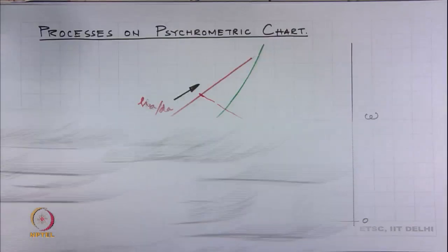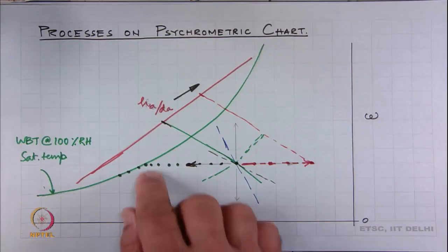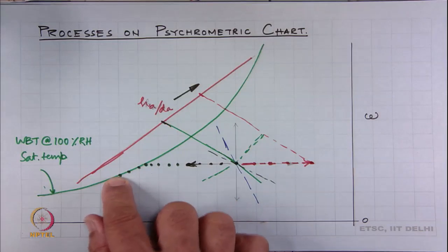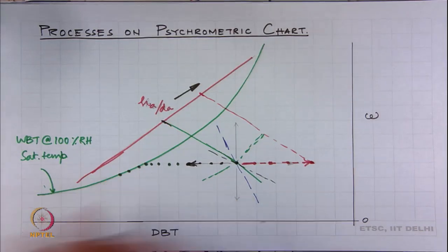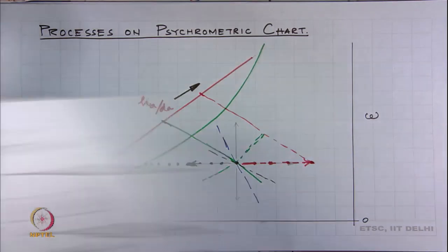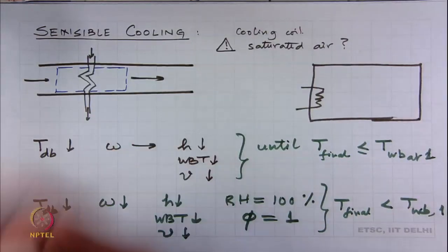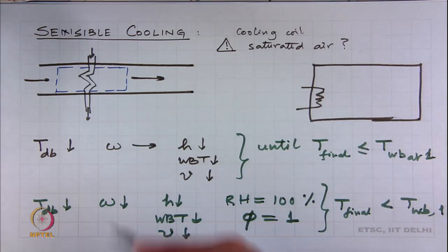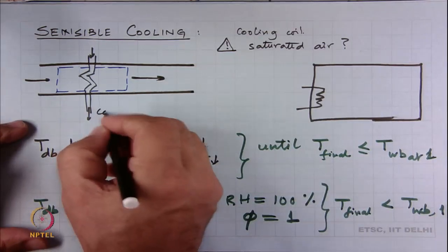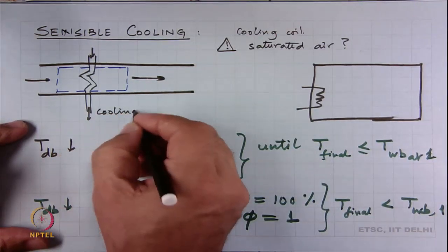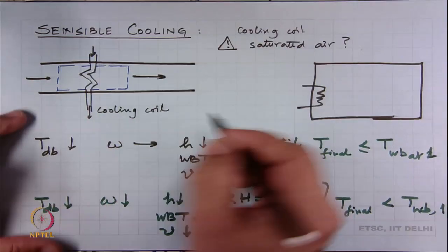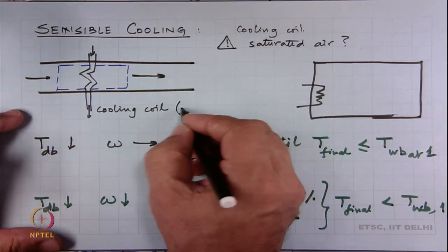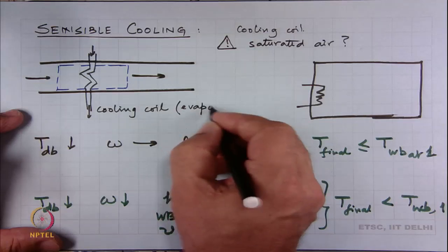And so, we now end in a slightly different situation, that we are also having precipitation. So, this is what one actually sees happening, and this coil that I have drawn here, this could be nothing but the cooling coil of an air conditioner, a window AC or a split AC, or what we may call the evaporator of the system.